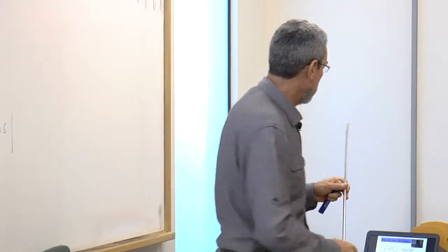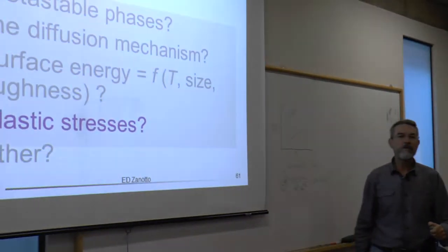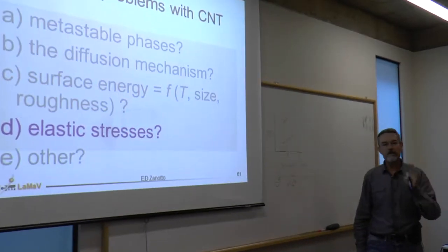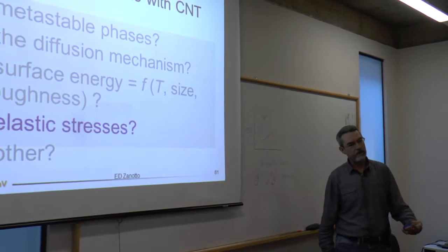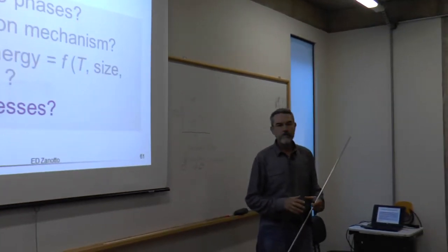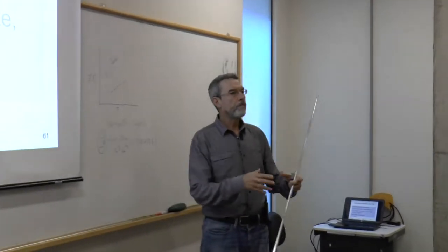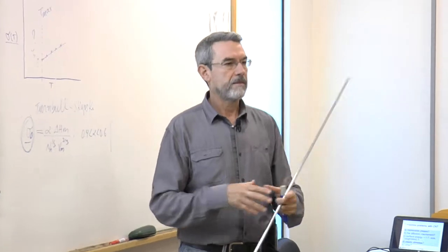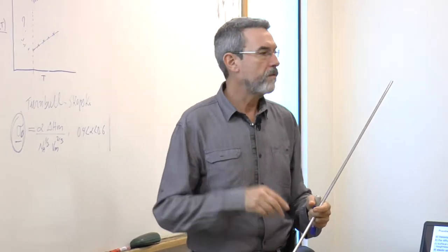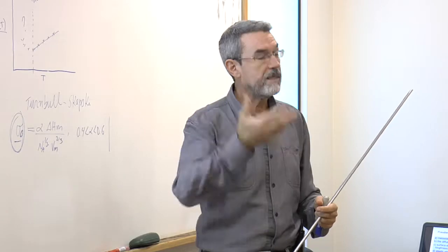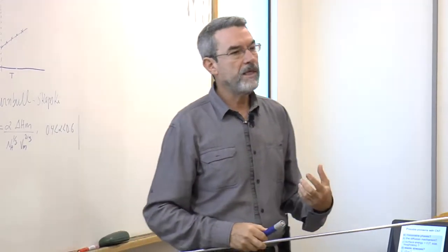Okay, so to summarize this whole story, the final missing point is, what's the effect of elastic stresses? If you recall in the first lecture, we have neglected the possible effect of elastic stresses because we assume that the crystal forms inside a supercooled liquid and then the liquid relaxes. The liquid relaxes and no longer has stresses, so they do not have any role on crystal nucleation. This is an assumption. So let's see what happens if we take stresses into account.